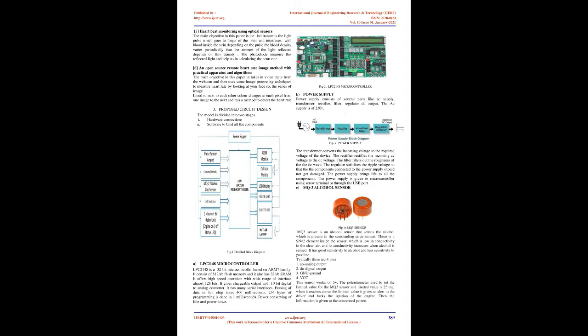2. Automatic driver drowsiness alert and health monitoring system using GSM. This paper aims to design for prevention of drowsiness and heart attack which may occur during driving, so it is done by implementation of an eye blink sensor for monitoring drowsiness and a pulse sensor for monitoring pulse rate. If the pulse rate is below the threshold value, then an alert message is sent to the respective person through a GSM module by using an 8051 microcontroller, so this makes the driver and his/her family members feel secure and safe while driving.